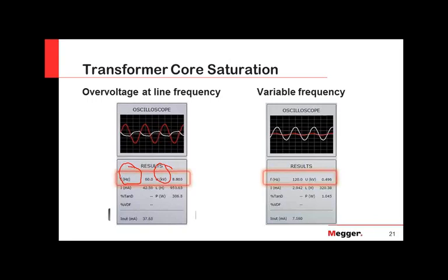We're getting close to 9 kV. Okay, and you can see even better now the effect of changing the magnitude. What we're doing right now is providing an overvoltage excitation to the transformer, and that's creating that effect. And now we're just cranking down the voltage.